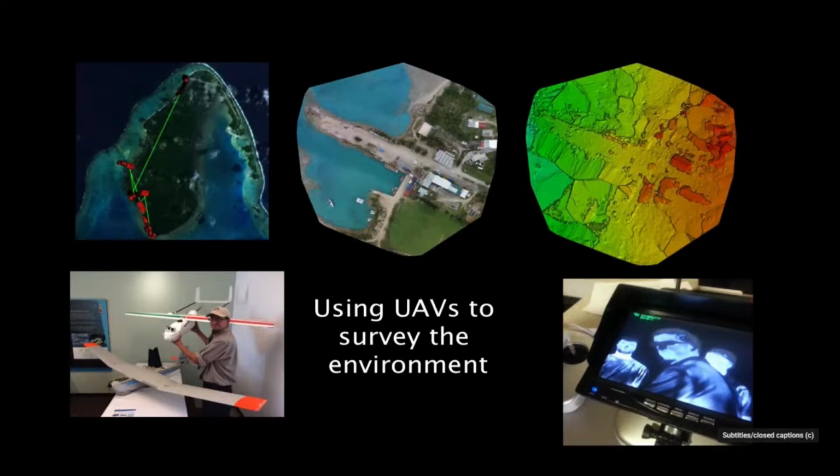And so what this is, is a DSM, a digital surface model. So this is actually taking that 3D model that we generated and associating a color with height. Your red is going to be your higher, whereas your greens and blues are going to be your lower. That's really useful in environmental science research because you can see, okay, there was this slope or this height of a mountainside, and there was the rock slide. And now in the next one, we compare it. So it was here, and now it's here.